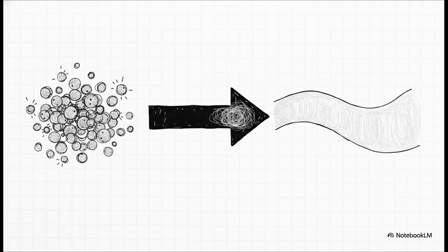Basically, as long as the volume of fluid we're looking at is large enough, specifically anything larger than about 10 to the negative 9th cubic millimeters, the random molecular variations just average out. Things like density, pressure, and temperature become smooth, continuous point functions. And this is a real game changer, because treating the fluid as continuous matter finally allows us to use differential calculus to solve real-world problems.